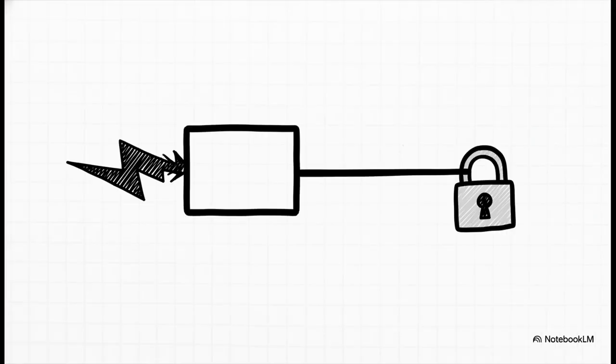But here's the kicker. The really crucial point is what happens immediately after. Once you cross VZ, you don't just get some chaotic surge. No, you get a controlled, completely stable flow of reverse current. The diode starts conducting backward, but the voltage across the diode remains incredibly steady. It basically locks that voltage into place, even if the external current is fiercely fluctuating.